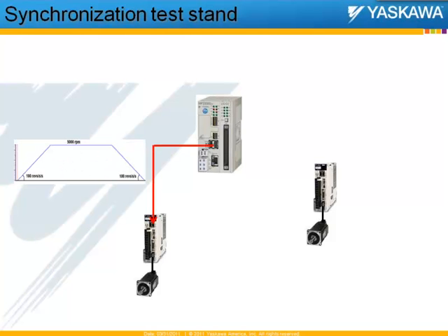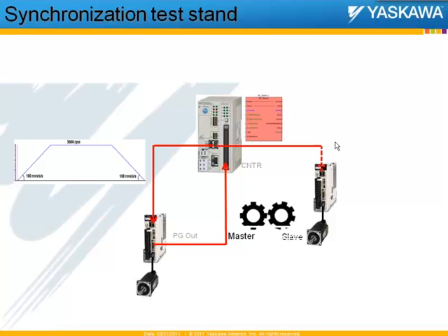The pulses generated on this axis were used as my external encoder master, fed into the counter circuit on a LIO card, and these signals were used as a master to gear to my slave axis. So in this test, I'm slaving my servo axis to an external encoder master, and the gearing ratio is 1-to-1 in this example.